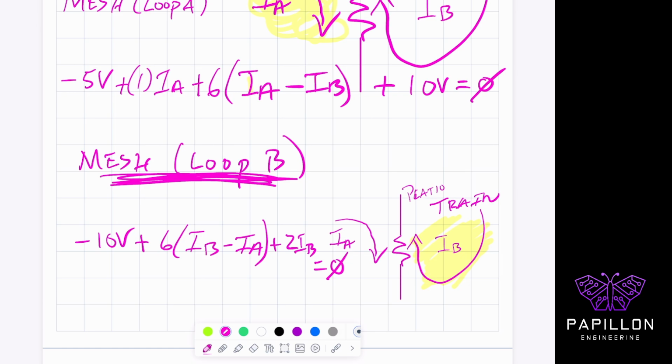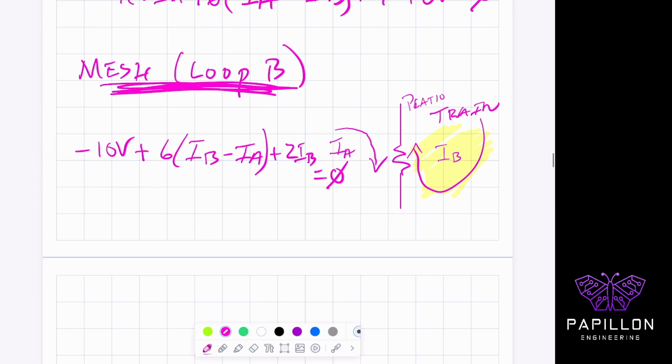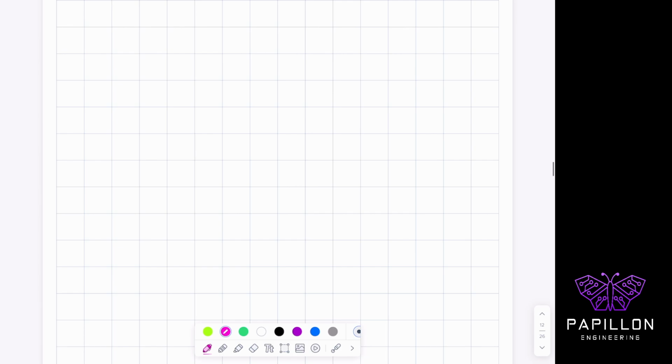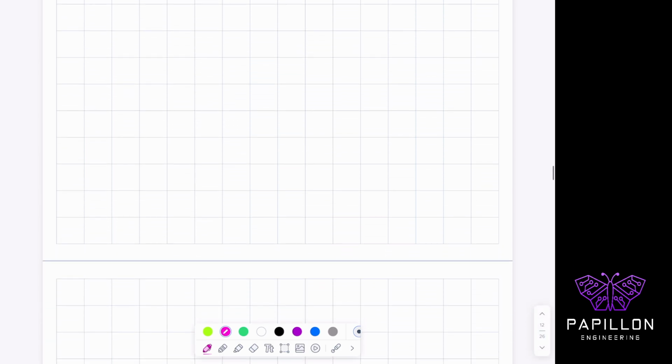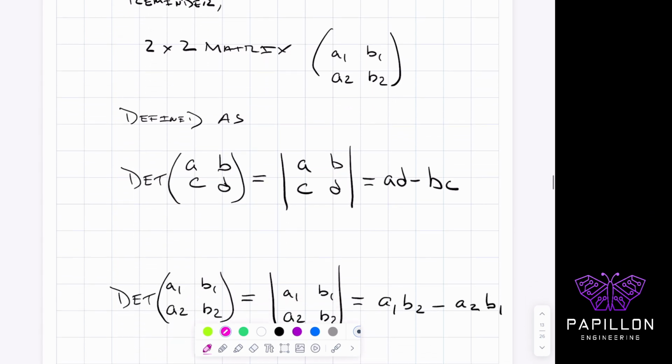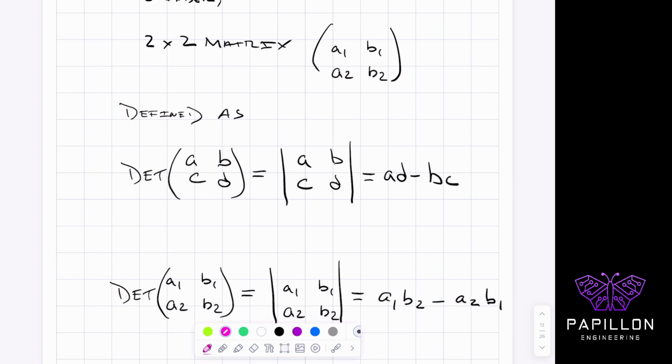The other technique that I showed you earlier comes in very handy when we work on something else called dependent sources or larger, more complicated circuits. You're going to need that technique in your back pocket to help you solve for that. Another thing I want to recommend, to solve these problems faster, instead of using the substitution method using math, I would recommend using a matrix. Matrices are hopefully easy. You're just going to create a determinant that's 2 by 2.